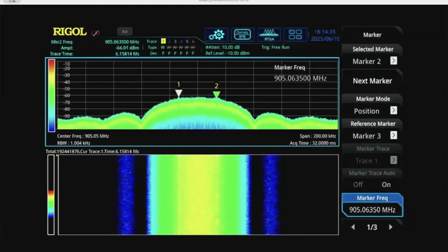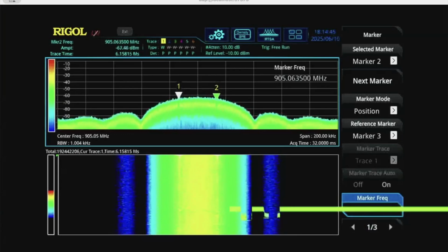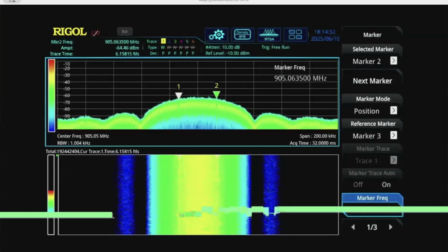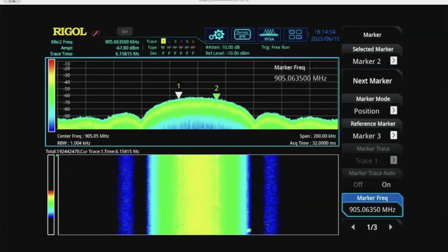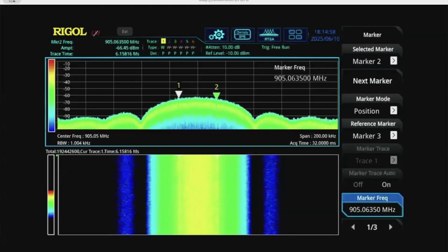And the first thing that you run into is that where the 1 and the 2 are isn't going to match up directly or exactly in the receiver as it did in the transmitter. And there's reasons for that. The clocks are different, the physical differences, drift, temperature, slop or whatever. And then also your channel can mess things up by quite a bit.